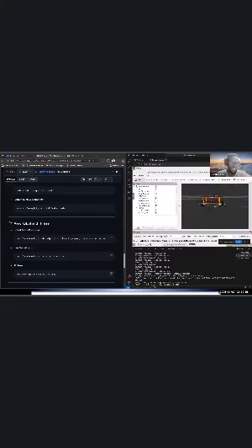We'll see the laser scan, we'll see the LiDAR beams. So this is the TF, and you can see the LiDAR is on top. This is where it is, over here. You see the tree, the base link. TF is basically saying what the transforms are, the relative transformations from the base link to the different sensors on the robot. I wanted to explain this because these are the basics.